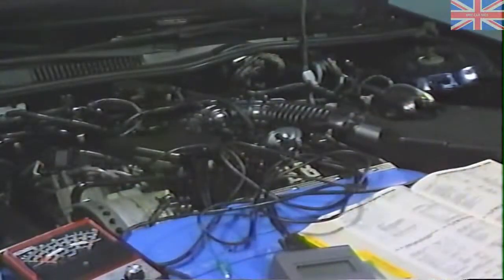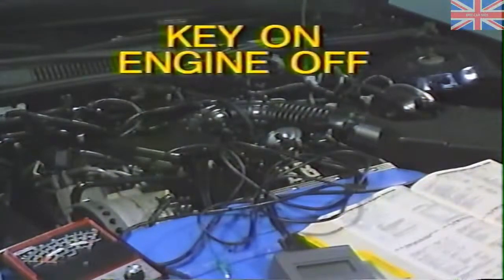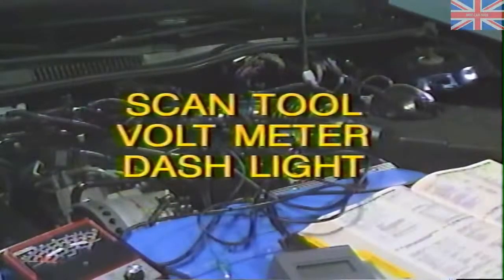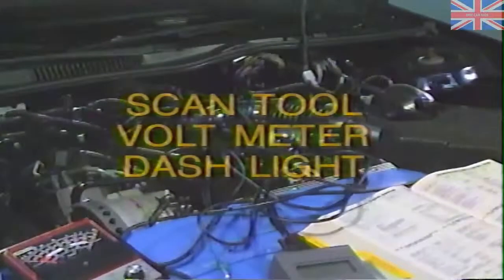Ford has a vast array of tests available. One is referred to as a key-on, engine-off self-test. Another one is called a computed timing check. Another one is called an engine running self-test, and even a continuous self-test. You also have a choice of test equipment to check the EEC-IV system. We will illustrate the use of a scan tool, an analog voltmeter, and the dash light to derive trouble codes.